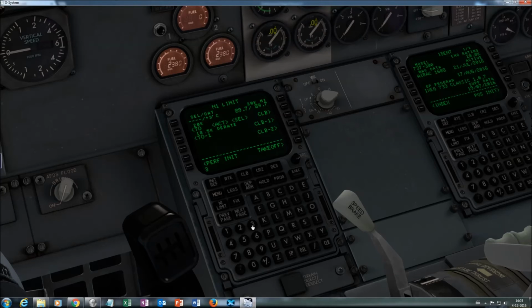So if I'm telling it that it is 37 degrees out there, which is nice and warm, it says, hey, now I only need 86.3, while previously it said it needed 89.7. And if you do that on every takeoff, and a 737 does a lot of takeoffs each day, that's definitely going to increase the lifespan of the engine. And you can also do it much higher or lower, but let's say 37 degrees. So that's okay for now.